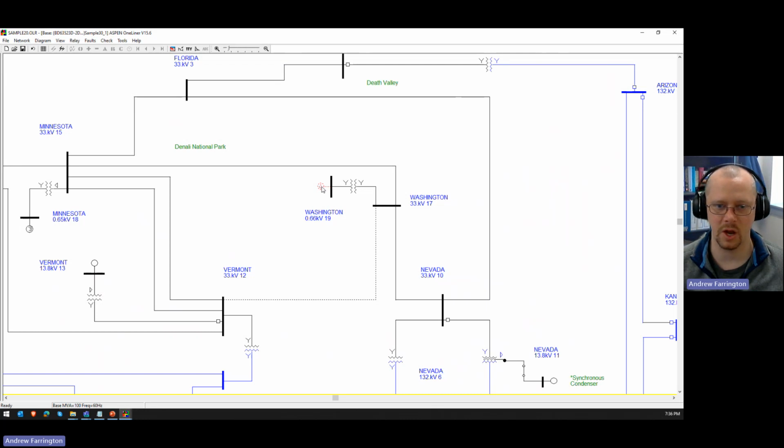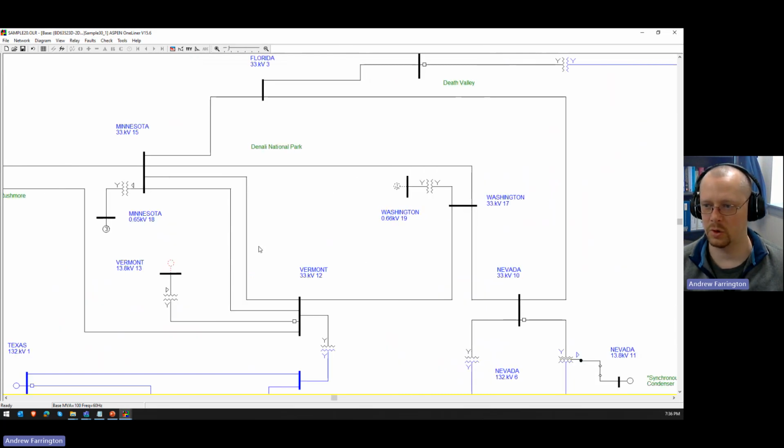I would argue that it's not. So you want to take that out and a line out, even though usually you only consider one contingency. Or maybe this is hydro and they generate in the spring when they've got the snow melt, and they don't have much in the late summer, early fall. So again, part of the year that's going to be out of service.